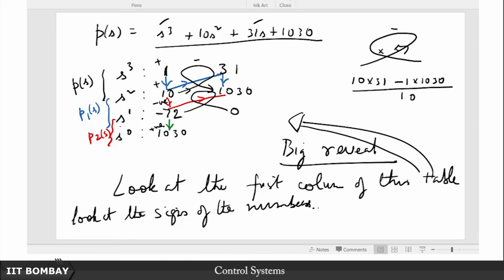So at some reduced stage of this polynomial you will encounter a polynomial whose coefficients have dissimilar signs, and therefore that reduced polynomial at that stage definitely does not have all its roots on the left half plane, and therefore no interlacing. And because interlacing works both ways, the original polynomial also does not have all its roots on the left half plane. Okay.